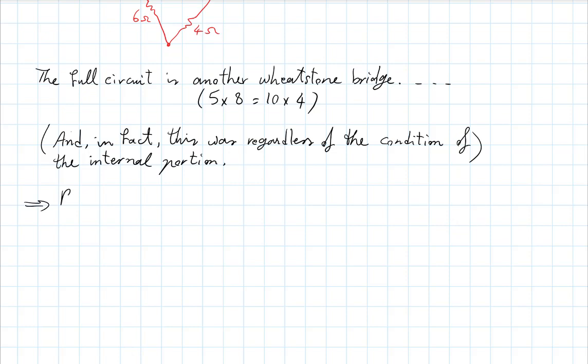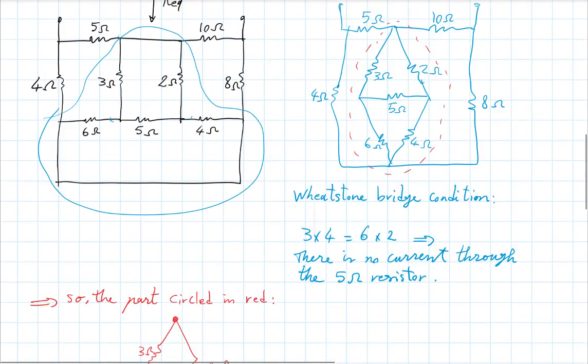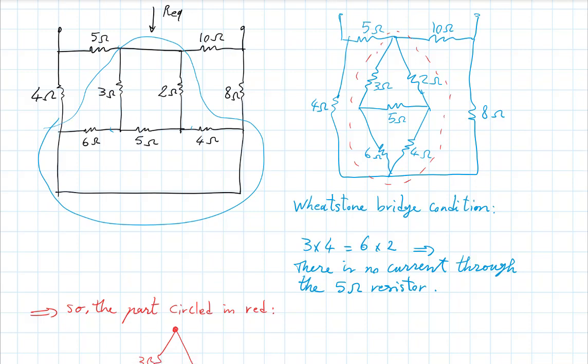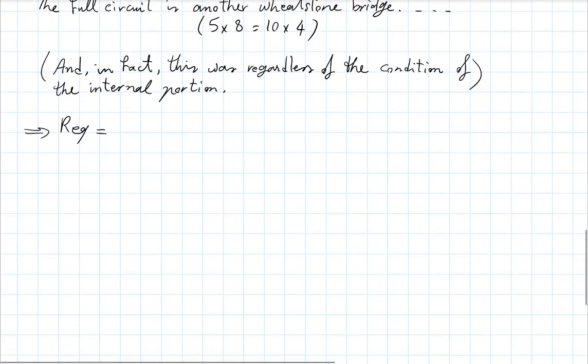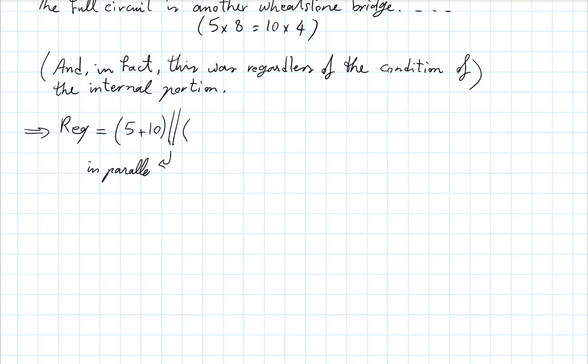So our equivalent is, like we said, 5 plus 10 in parallel with 4 plus 8. So that's the sign for in parallel. Okay?